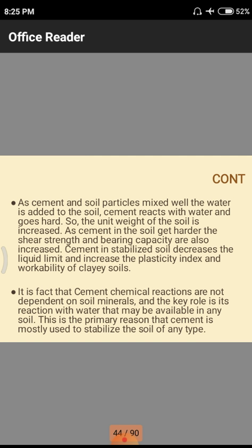Likewise here also, after the reaction is over, the total cement content which has reacted with the soil will give a huge amount of hardness and strength properties, so the unit weight of the soil increases. Normally unit weight means density. In the previous case, the soil has only particles without this cement. That means in that case, the density is very less. After mixing the soil with the cement content, automatically density increases as well as strength increases. Both are in an increasing position.